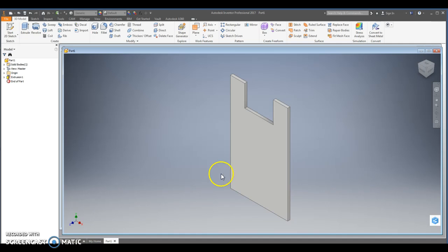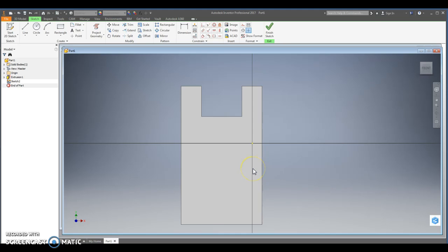So what we need to do is actually we need to go back to our 2D sketch. So click that, and then click the front of our climbing wall. This allows us to draw any features we want to add. So in this case, since we're making a hole, most of you choose the circle tool, but that's not right. What we want to do is choose the point tool. So we choose point, and then you can just place a series of points on the climbing wall.